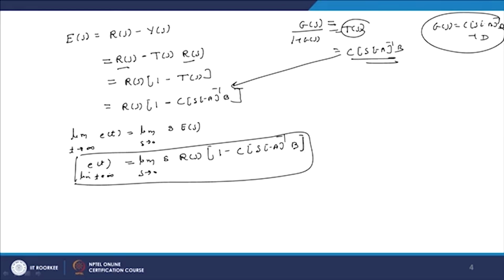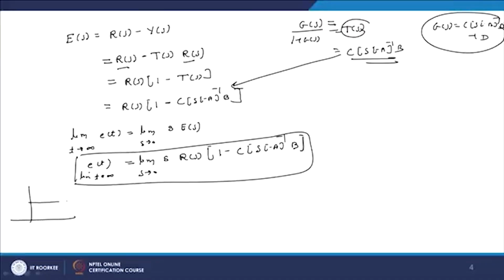Now, why we are taking t tend to infinity? Because in time domain steady state means at t tend to infinity, that is time is infinite, that means when we take the response of any plant, this is t. So, when t tend to infinity, that is we are moving at last end state, steady state. Earlier part is the transient part.